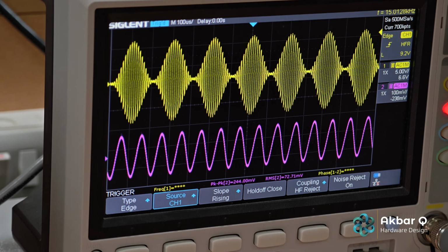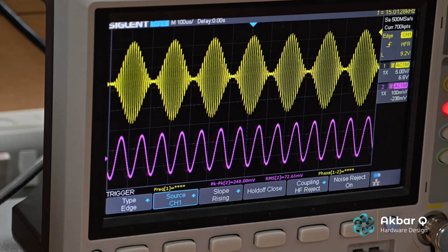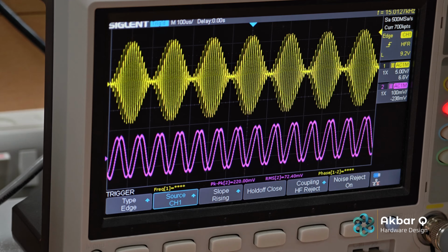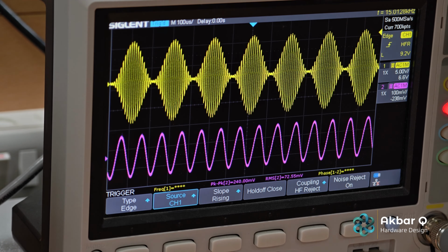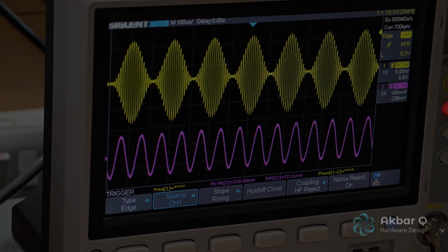Then at the output we basically have one low frequency sine wave, and that is it when it comes to the demodulation circuit. This is one of the most basic demodulation circuits imaginable. But the downside is there will be an extremely large amount of losses the more filter elements we add. In this case, since we have a fifth order filter, the output voltage on the pink waveform has a very small amplitude, so small that it might not be usable. Because this is a high sensitivity oscilloscope, we are able to measure it quite easily. But if it was not the case, it would be quite difficult to measure. So again, thank you.